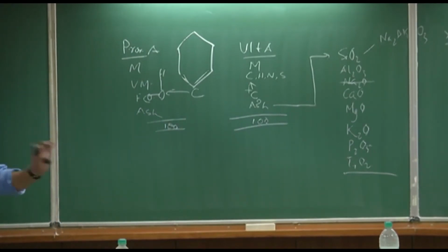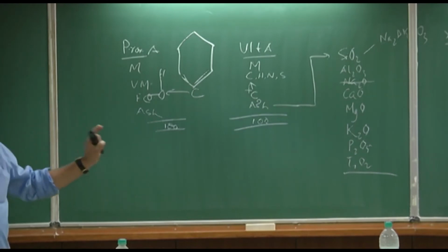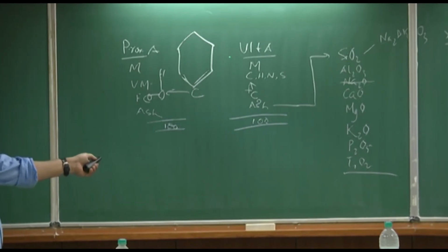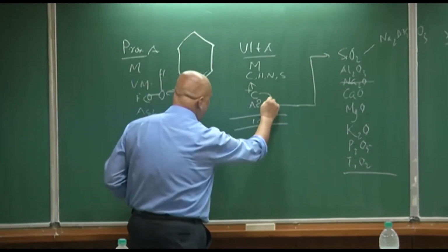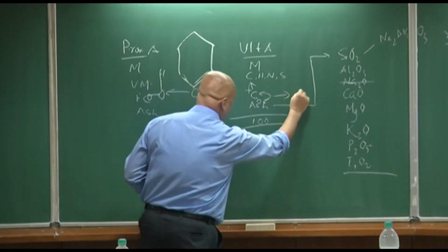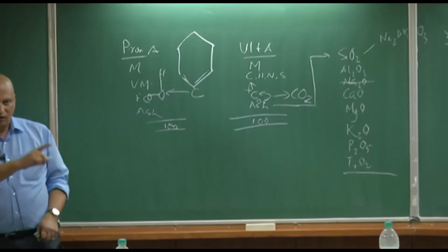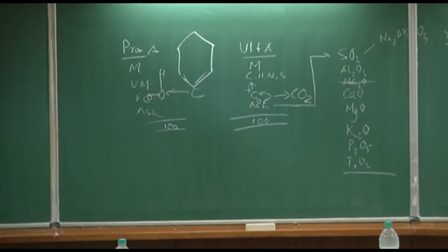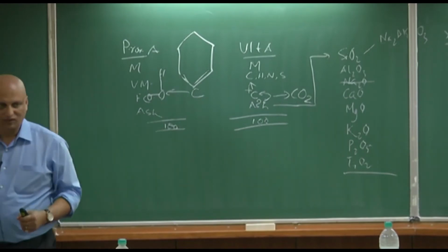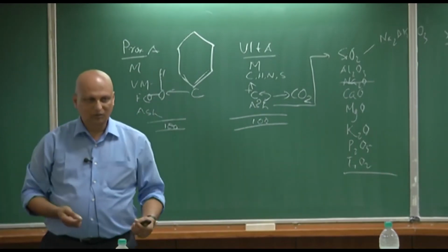So the oxygen is shown as an element here, but actually it is not elemental oxygen that will come out. When you heat it, it will come out together with some of this carbon as CO2. So this carbon will no longer need any oxygen from the primary air or the secondary air. So you'll need less oxygen to be supplied.